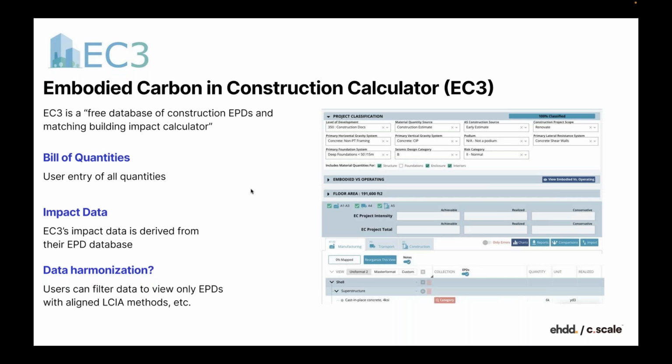Awesome. So in EC3, the bill of quantities is user inputted. If you know it's in your model, you'll put it in there. But if you forget to put the screws, say, in your wood stud wall, it won't remember for you. Whereas something like Tally that has its smart lookups will help do some of that filling around the edges. So typically in our workflow, we're moving data that we've developed in Tally or One Click into EC3, having helped fill all those holes in the bill of quantities earlier on by the time we move it into EC3.